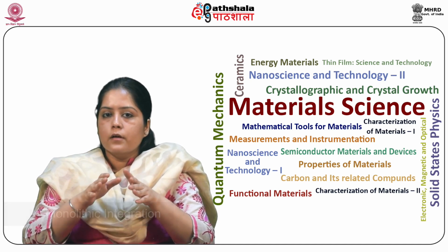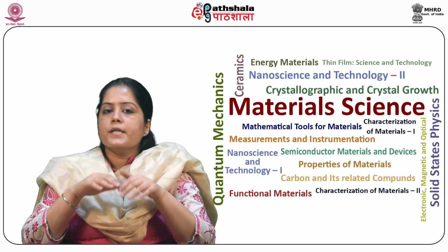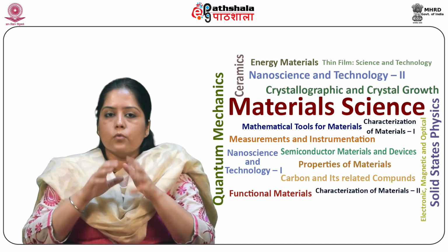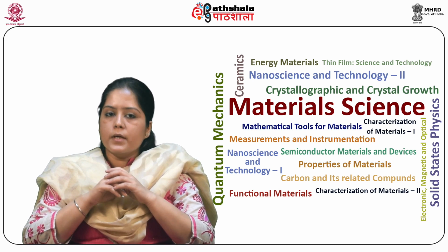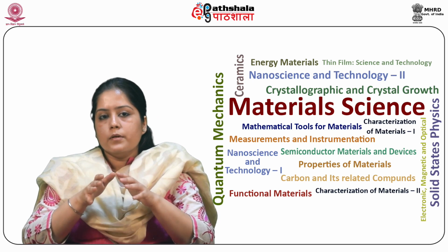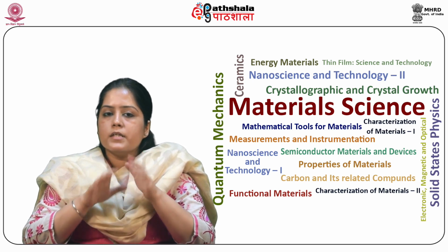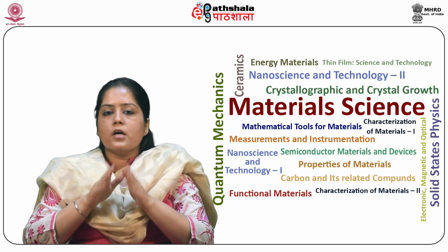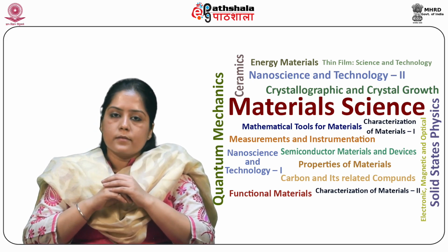Monolithic integration of individual cells is simple and is done by selective laser ablation, which allows for module voltage optimization. Silicon and hydrogen, they are abundant. Material can be doped P or N type with boron or phosphorus respectively. The material possesses the necessary electron and hole transport properties for PIN type solar cells.